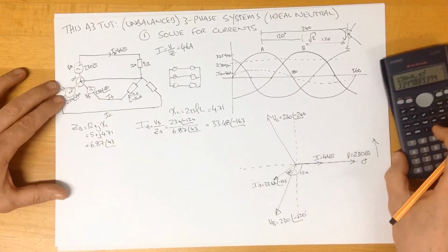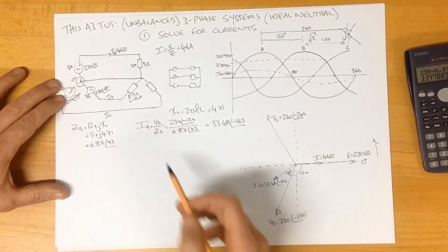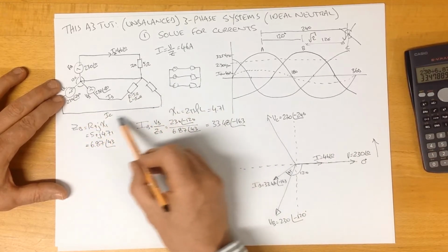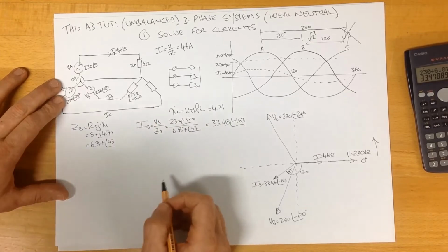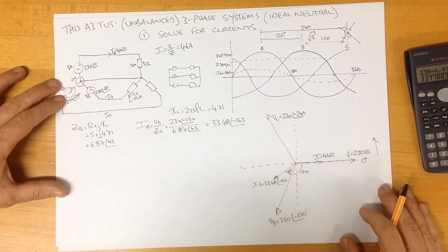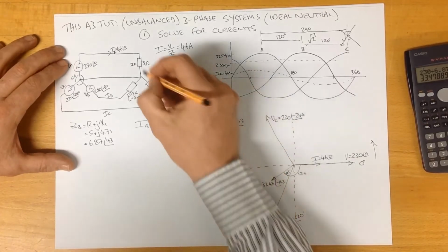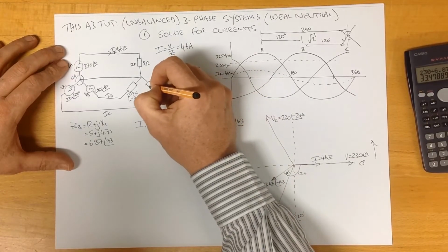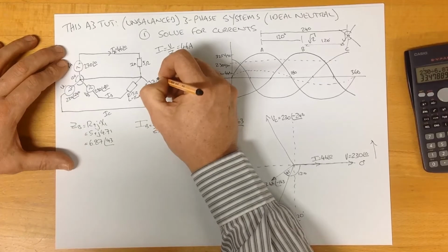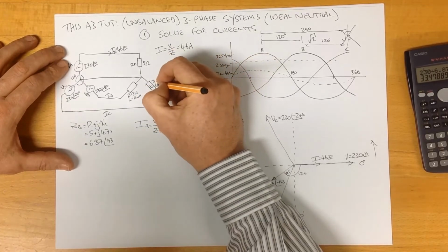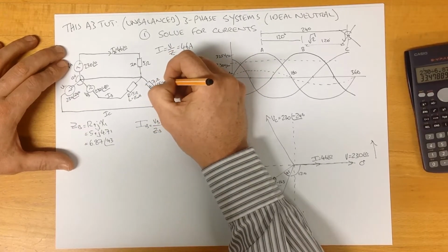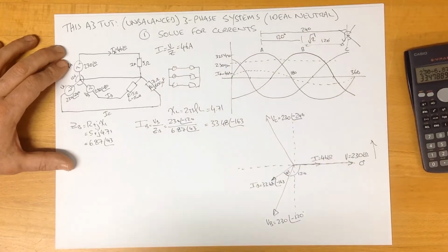We can now go through and do the exact same process to find out the current flowing in line C. So for line C, what I've decided to do is we'll put in a value of 7 ohms of resistance, ZC, 7 ohms, and we'll put in 600 microfarads.